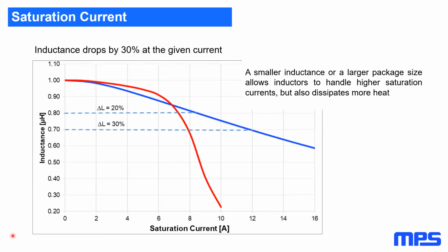From the magnetic point of view, when we use a core material, we can intensify the concentration of magnetic flux. So this density will be much higher when we have a high permeability core material. More magnetic flux, more saturation current. We discussed also losses, core losses, copper losses, the currents, rated and saturation current, and some layout recommendations.